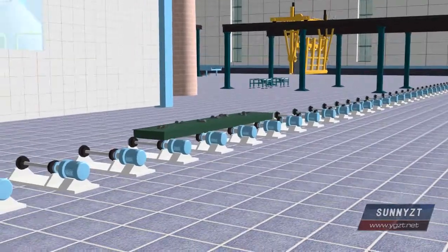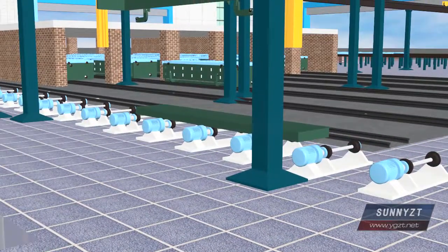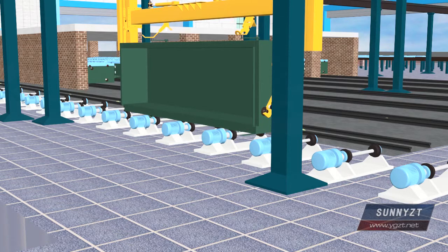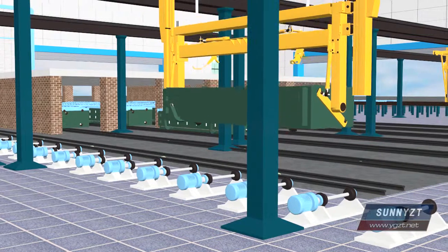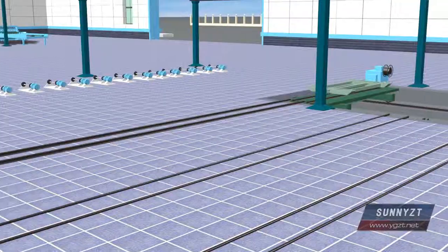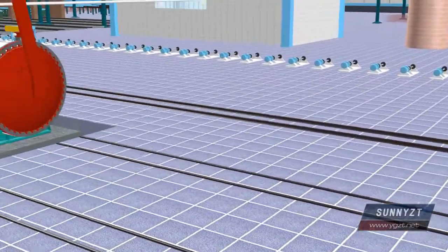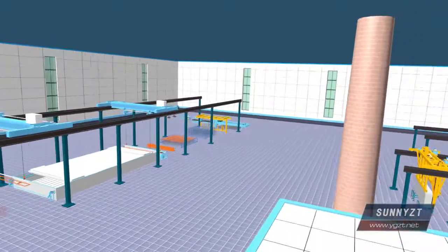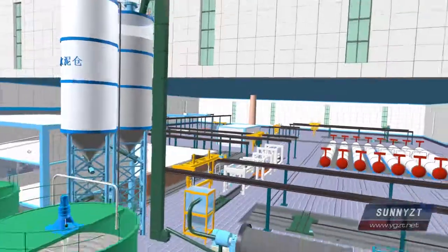Meanwhile, after processing on the side plate conveyance line, the side plate, having discharged the finished product, combines with the empty molding box again. The steam curing trolley returns to the front of the kettle and does marshalling again. The production line of Sunny ZT aerated concrete panel will keep repeating the above-mentioned production process continuously.